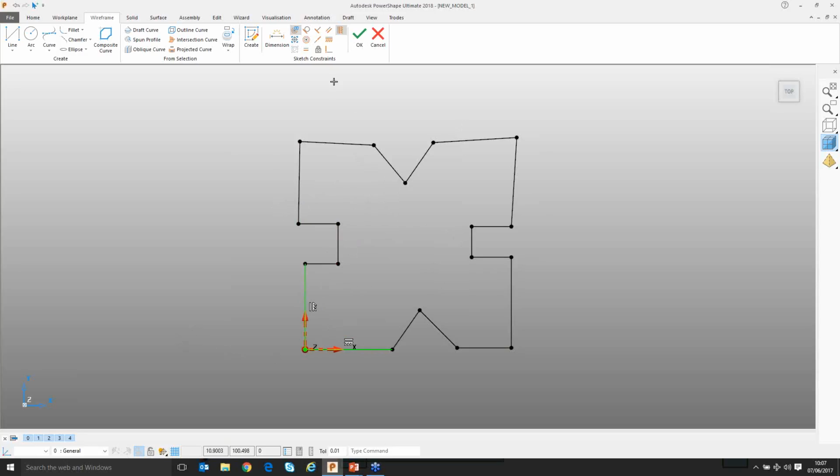So let's have a look at some more. That was horizontal and vertical. Maybe what I'd like is a perpendicular option. And for that, I'll go to maybe this corner and this corner and suggest that that has to be perpendicular, and here also needs to be perpendicular. So that's effectively a 90-degree corner. So let's go on to do some more.